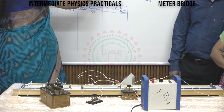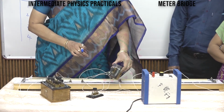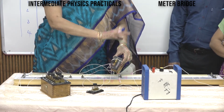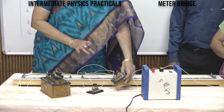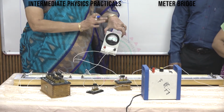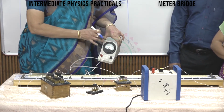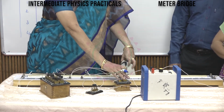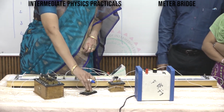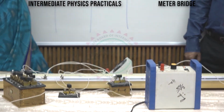And what is this HR? HR is this 5K, 5000 ohms. High resistance. This helps us to protect this galvanometer from damage. This galvanometer is a very sensitive device. There is every possibility if more current passes, it gets spoiled. So to protect it, we have connected this high resistance in the circuit. And this is the key.